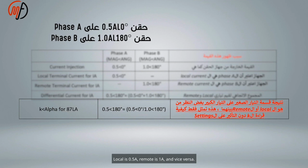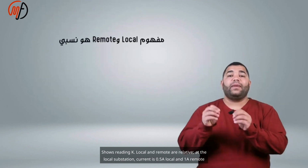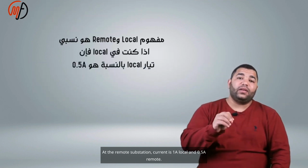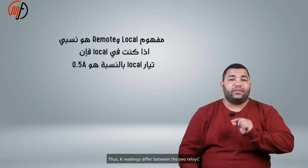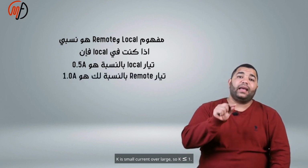Local is 0.5A, remote is 1A, and vice versa. K is small over large current, always less than or equal to 1. This shows that reading K, local and remote are relative. At the local substation, current is 0.5A local and 1A remote. At the remote substation, current is 1A local and 0.5A remote. Thus, K readings differ between the two relays. K is small current over large, so K is at most 1.